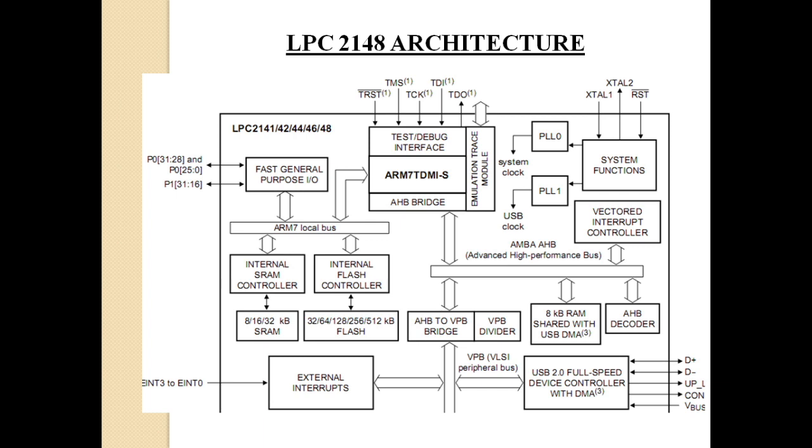Then after a few years, EPROM was developed. That means you can erase that and you can rewrite it. How will you erase it? Using something known as ultraviolet rays, right? So there will be a separate EPROM eraser for erasing EPROMs. So how will you apply the ultraviolet rays to the data which is stored in the IC? Ultraviolet rays are a light radiation.